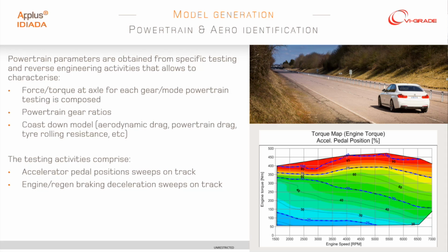So at the point where the transmission is shifting gears, in case of an automatic transmission, we can also get the different gear ratios, and we can characterize a very simple yet powerful model of a complete truck. So we can identify the drag coming from the powertrain, and then we can estimate which is the drag that will be coming from things like the aerodynamics or the rolling resistance of the tires themselves.